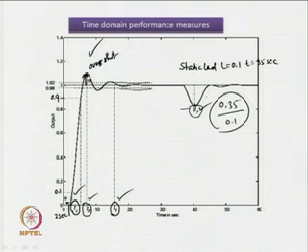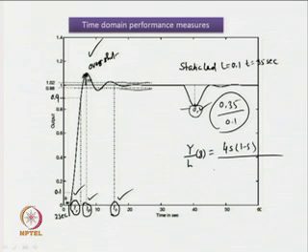To find that, again you need to find the closed loop transfer function with respect to the static load input, which can be given as y upon L s in the form of 4 s (1 minus s upon 2) upon s cubed plus 2.5 s square plus 1.262 s plus 0.262.